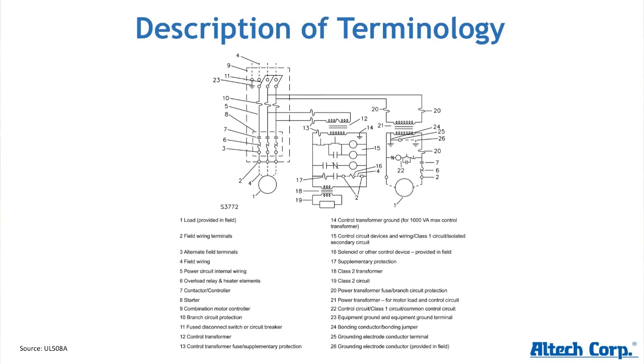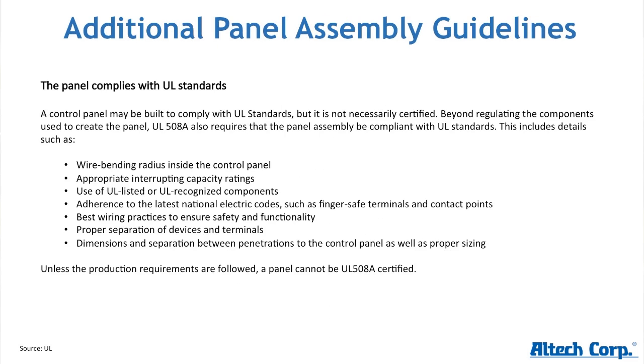You also should, obviously, follow the National Electrical Code or maybe some local installation guides or the guidance of the inspector at your local site, if that is an issue. Then again, as I mentioned earlier, it's all about safety. So make sure it's safe and functional, and make sure that the control circuit and the power circuits are visually separated.